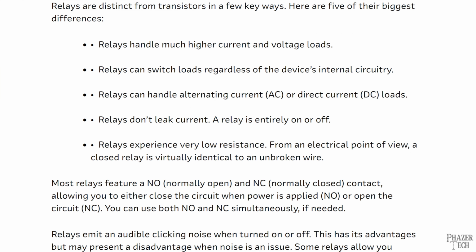The main problem with transistors in applications where you need to power other devices is that transistors aren't 100% efficient, which means you'll be wasting power in the transistor itself. And not every transistor is able to handle high-powered loads either. The transistors that can handle higher loads can be fairly expensive, so cost becomes a factor as well.